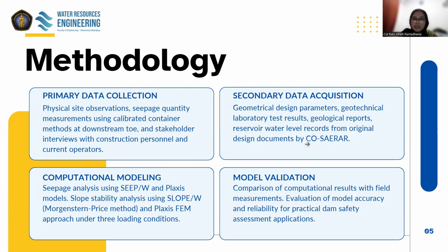For the methodology, there are 4 steps. The first step is the primary data collection. The primary data are the physical site observation, seepage quantity measurements using a calibrated container at the downstream toe, and stakeholder interviews with construction personnel and current operators.